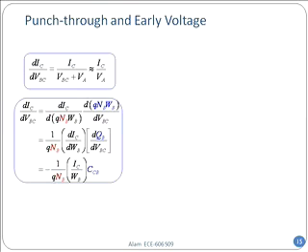And the QNBWB, what is that, by the way? Q is charge, NB is the doping in the base, right? WB is the width of the base. So that is the amount of charge. That is the amount of majority carrier charge I have in the base region. So I'll call that Q sub B. All right. Now I know that Q sub B, right? Because I know NB and I know WB from the geometry of the transistor.